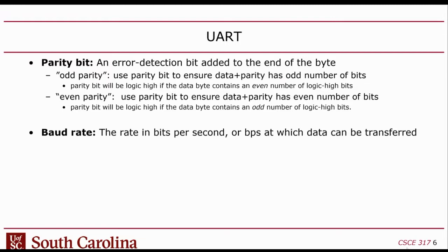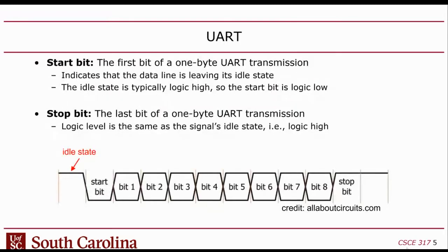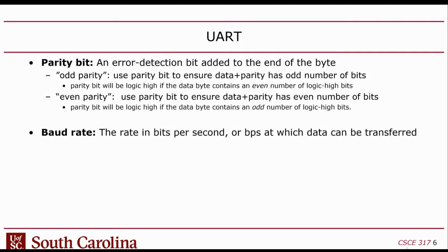Now, keep in mind that with UART, and I think with all the interfaces we're going to talk about, the assumption is that the bits are transmitted consecutively in each bit time. So there's no way to stall the channel. There's no way for the transmitter to send 2 bits and then decide it wants to wait a little while before it sends the rest. Once you commit to a transaction, you have to go through the whole thing. You have to send exactly the number of bits that are expected in consecutive clock cycles, if a clock cycle is the amount of time allocated for each bit in the channel. So these are all consecutive; you can't stop and start.